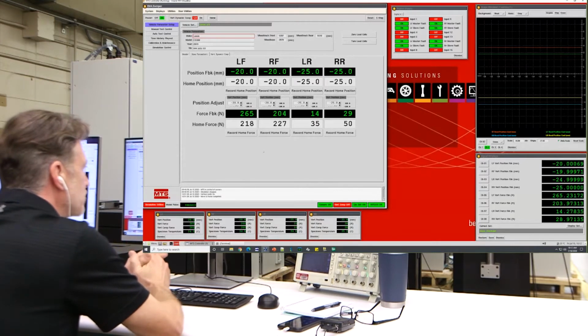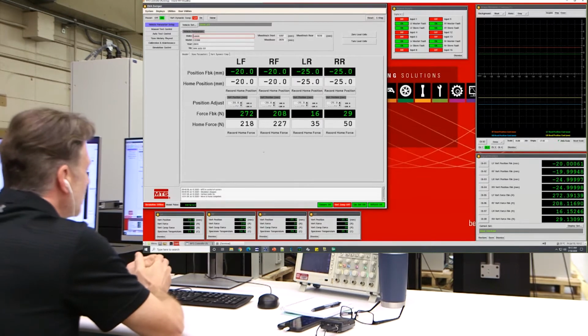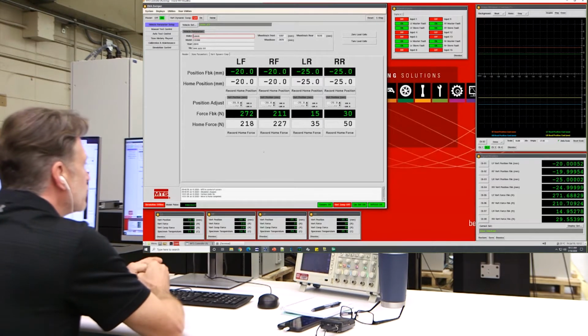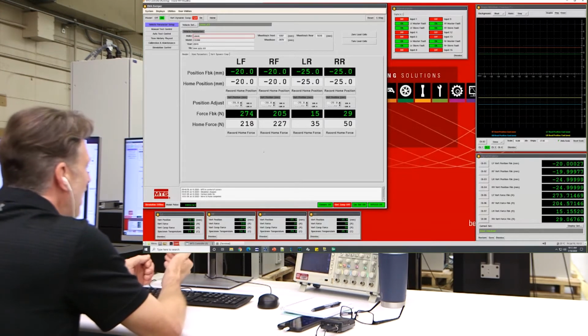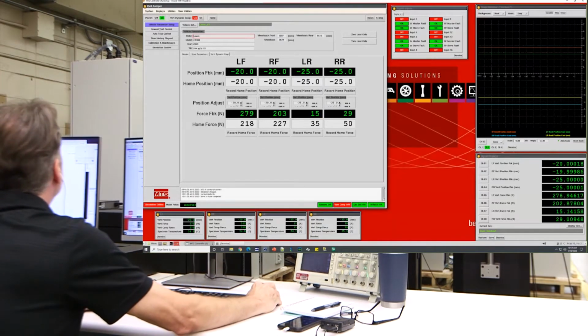When we use an mHIL system, taking a physical component and putting it in the loop, closed loop with the model, we want to include as many components as possible because those are not represented in the vehicle model. So we'll include the lower mount, the upper bushing mount, so that all of that is in the force that is going back to the vehicle model.